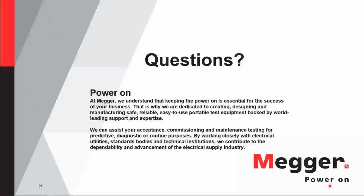Thank you, Moni. Next question: will the DGA test be sufficient over the dielectric breakdown voltage test? I guess this is a continuation of one of the previous questions. Can I just do one test and not worry about the other? Our response, based upon the experience that we have, is that each test has its own place.